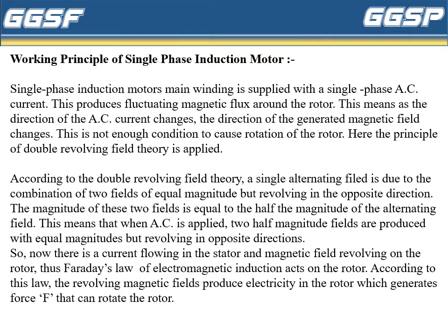The working principle of the single phase induction motor. Basically, this single phase induction motor works on Faraday's law of electromagnetic induction. Single phase induction motor's main winding is supplied with a single phase AC current. This produces fluctuating magnetic flux around the rotor. This means as the direction of AC current changes, the direction of generated magnetic field changes. This is not enough condition to cause the rotation of rotor.